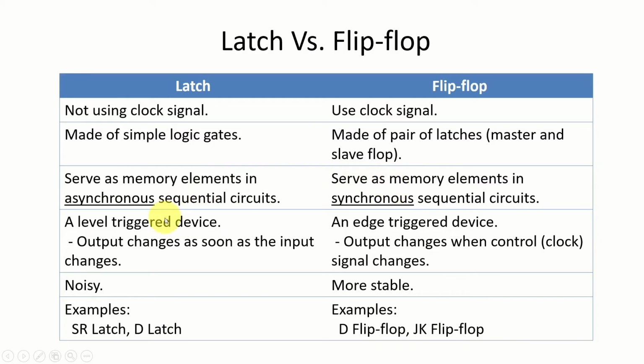And also latches are level triggered devices, whereas the flip-flops are edge triggered devices. So what is meant by a level triggered device? Whenever you change the input, immediately the output changes. Of course, it needs that saturation time, but it happens immediately. But when it comes to flip-flops, the output changes when you change the control signal. So that is another difference between latch and flip-flop. Of course, we are going to understand those things when we are discussing the flip-flops. But this is just an overview, some insight into the flip-flop as well.